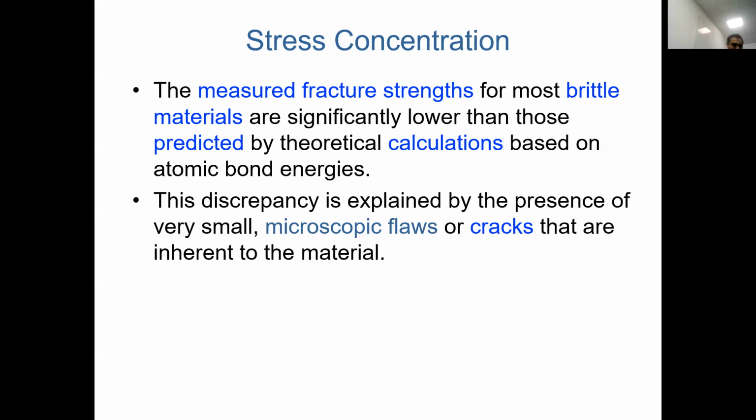Now, the reason they fail at much lower forces is because in theory, we didn't consider microvoids. We didn't consider that when someone is making the object, casting or whatever, there are air bubbles entrapped. There are some impurities. There are some flakes in there. There is some other material. So we don't consider that, and hence the results are a little bit different. Okay.